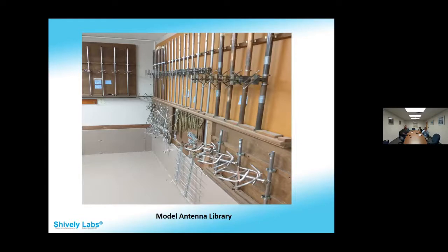Am I still sharing this photograph here of the model antennas? Yes. You can see here, on the bottom, hanging over the frost wall, some log periodic antennas. What's important here is the dimension of the boom, the diameter of each element. The diameter is very important. The relative location to each other, and the overall length need to be scaled very, very accurately.